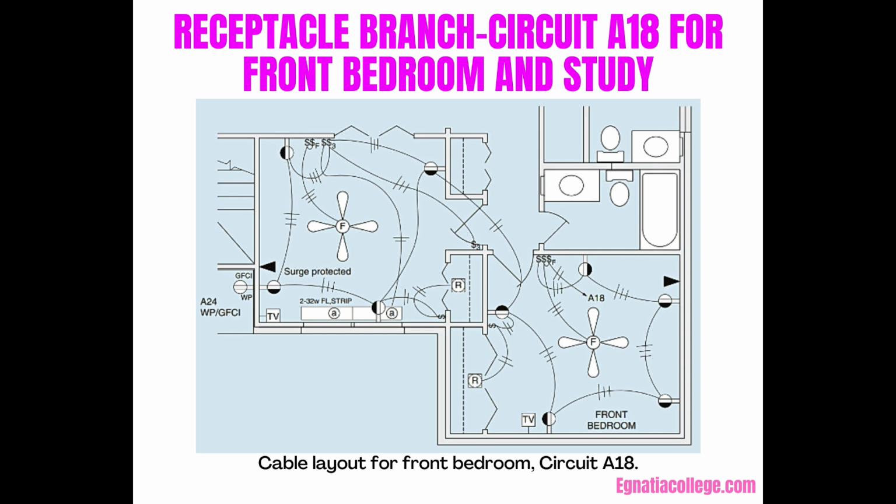Receptacles in a dwelling must be tamper-resistant, as per Rule 26-706. These receptacles must be clearly marked tamper-resistant, or TR. Radios, televisions, and other electrical items not intended to be controlled by the wall switch will be plugged into the unswitched, hot continuously, half of the duplex receptacle.